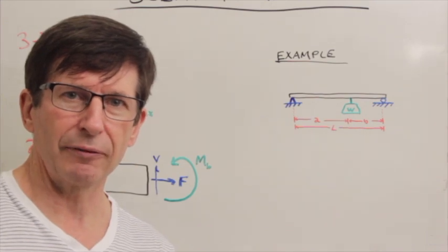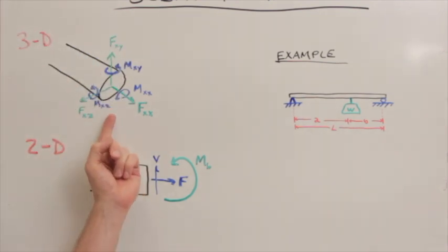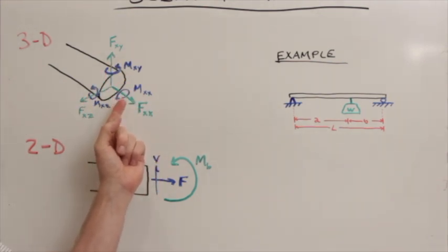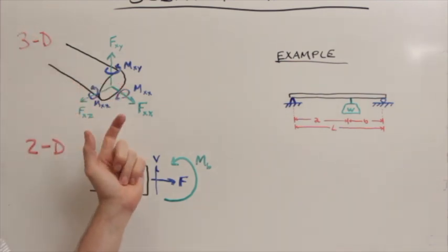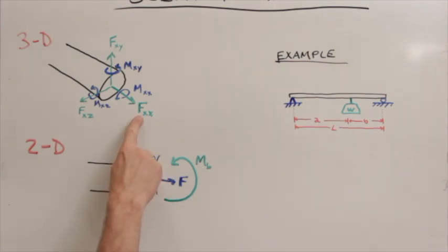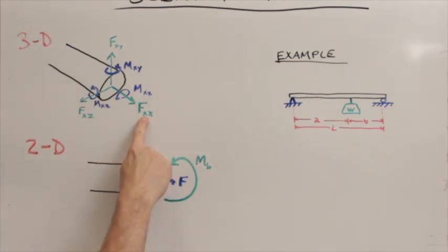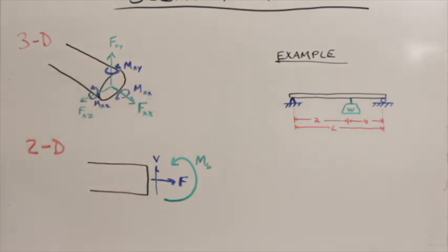As we dive in to think about the forces and the moments on these structures, we need some way of having a common language to speak and a convention. Our convention in 3 dimensions is for the forces, here shown in green in the 3 coordinate directions at the end of a long beam, and then the 3 moments about those axes. Forces are F, moments are M, with the first subscript representing the face on which the forces are acting and the moments are about.